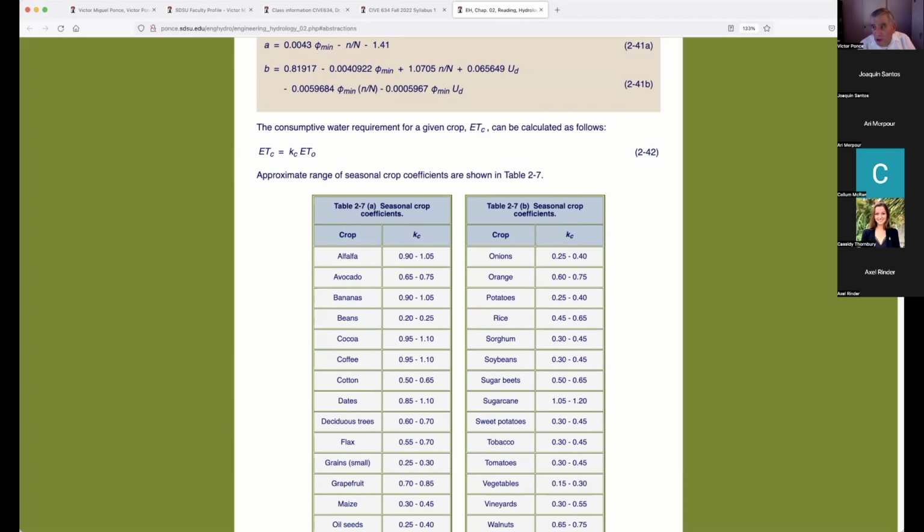We got to drain the soil. If we don't drain the soil, eventually the people doing the irrigation are going to go out of business. The numbers for the drainage, it's called the leaching coefficient, could be maybe 10, 15, 20%. That has to be calculated.